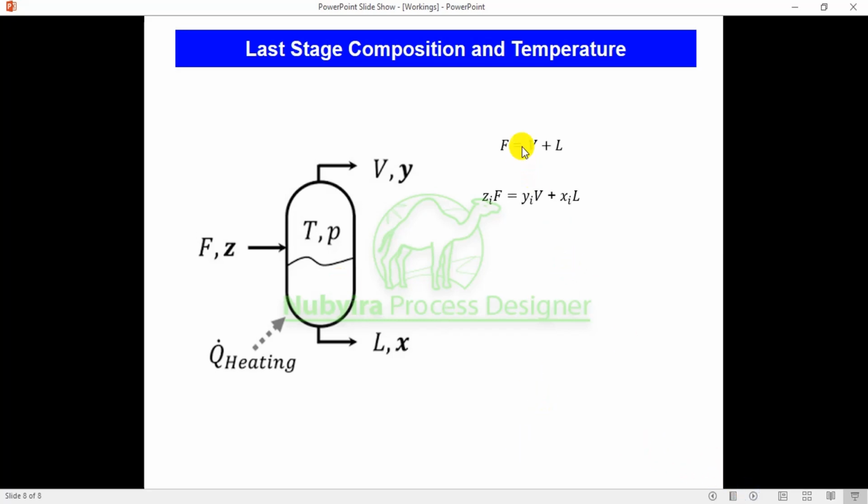So the material balance is doing the same thing for this system too, you understand. From the Raoult's law, you have the y, that is for the vapor-liquid equilibrium of this mixture, you understand, is going to be Raoult's law. So you can make y the subject of the formula, let's do it for the light component, that is benzene. If you make y the subject of the formula, you have y P is going to be P sat, then x, you understand.